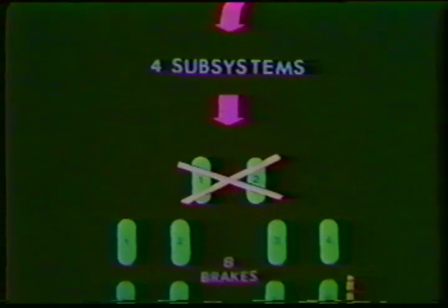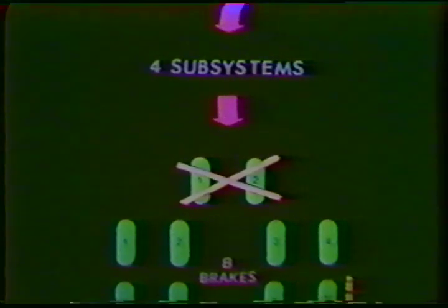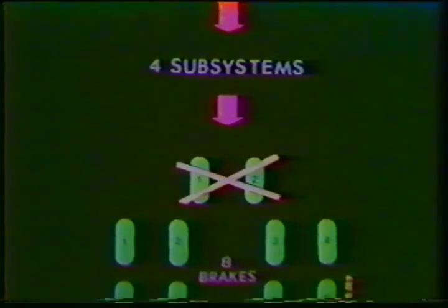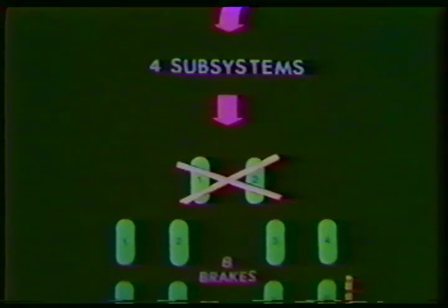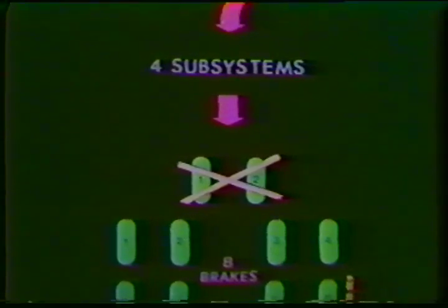The brake system is divided into 4 subsystems: the normal brake system, alternate brake system, emergency brake system, and the parking brake system. As we mentioned earlier, only the main gear wheels are equipped with brakes. Each brake consists of 2 sets of pistons, green system pistons and yellow system pistons.